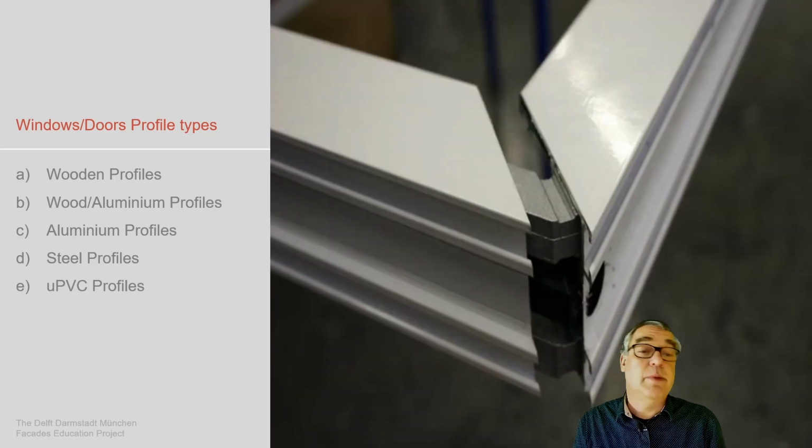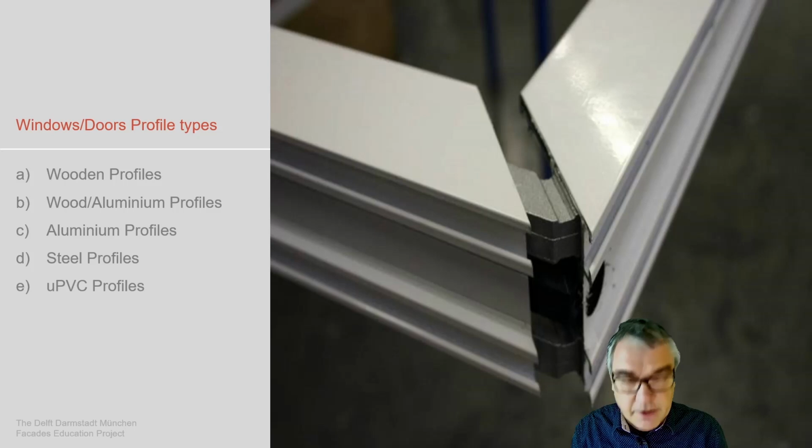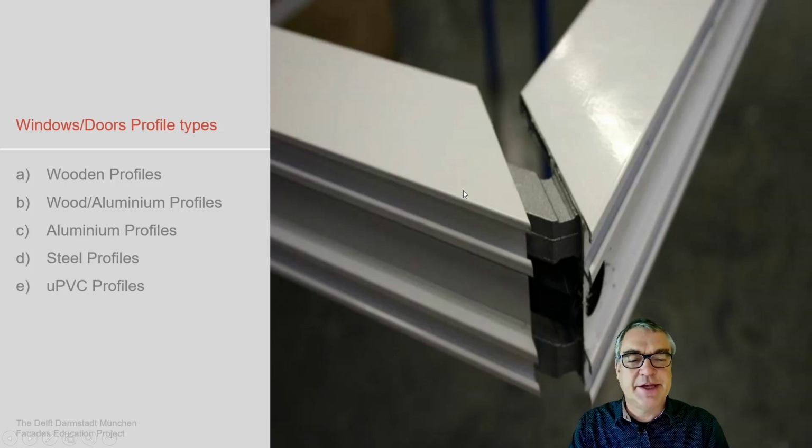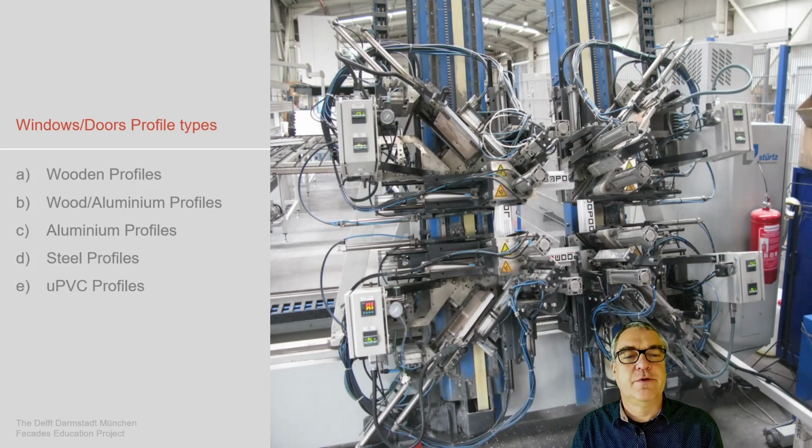a system. The aluminium system is mainly done with two of these aluminium units, which are then connected with an L-shaped corner cleat. So this corner cleat is brought in position, then fixed by screws, and keeps the edge stable versus the